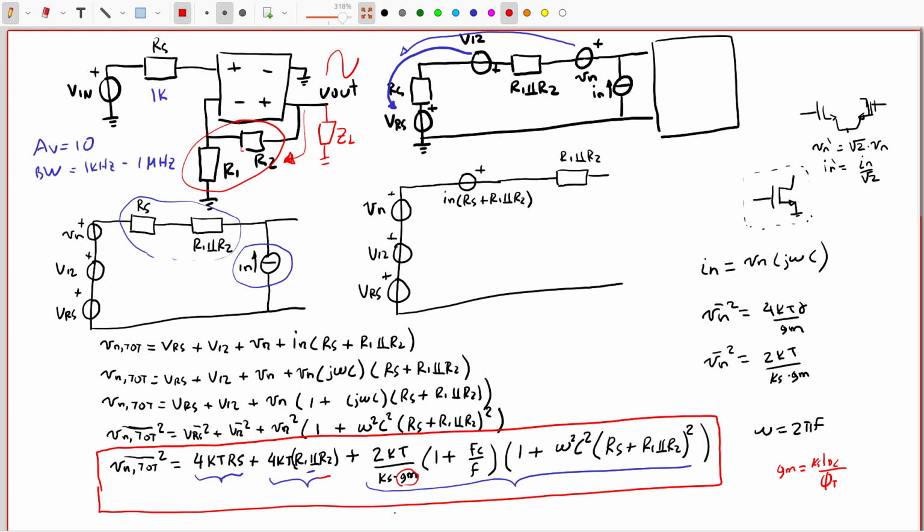It will be required to put current in order to increase the transconductance, and I also should remember that gm in strong inversion, on the other hand, is proportional to the square root of IDS. So it is very costly to increase the transconductance to try to keep this value low in strong inversion. So I have to be careful how I generate this transconductance.